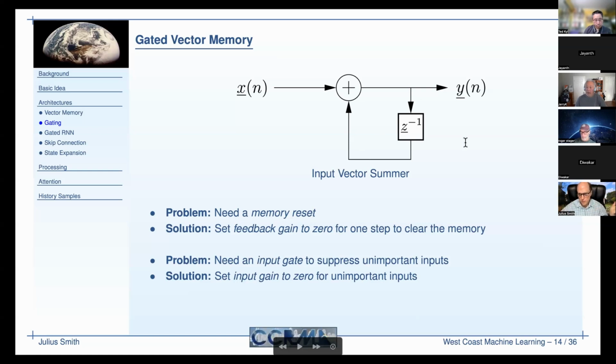This is a one-pole filter structure. It's a direct form filter structure. There are also other structures such as the ladder. In the normalized ladder, you have the property that when you feed in white noise, the variance is the same at every state in the filter. So it normalizes the state, and that's really valuable when you're stuck in fixed point arithmetic.